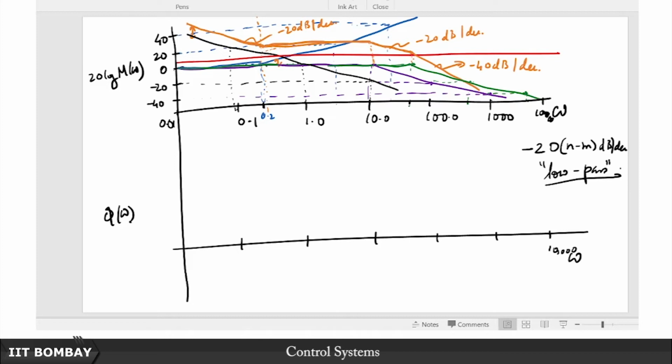So eventually you will see that this Bode plot of this control system, for a system that is actually strictly proper in fact. A control system is generally strictly proper, as we've discussed so often in this course, right. So for such a control system you will see that it will always have a low pass characteristic, in the sense that it will try to amplify lower frequencies and it will always attenuate frequencies beyond a certain cutoff point, at higher frequencies. So that's why we say that control systems are generally low pass in nature.